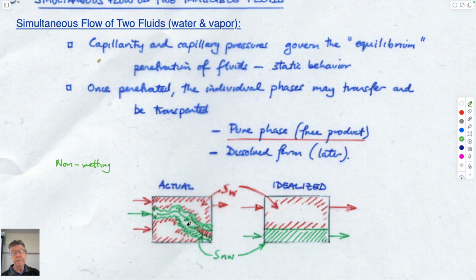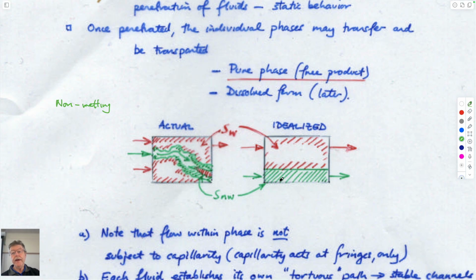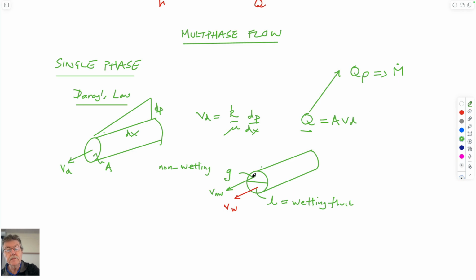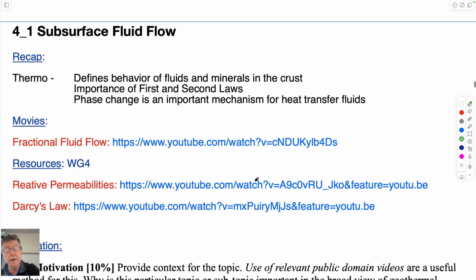If you take this and imagine it being centrifuged, so that you could move all the grains and the fluids that those grains contain into two different parts of the reservoir, so you have a non-wetting part and a wetting part, then what we can do is individually look, as we looked at the previous cartoon, at flow just in the wetting phase and flow just in the non-wetting phase as separate.